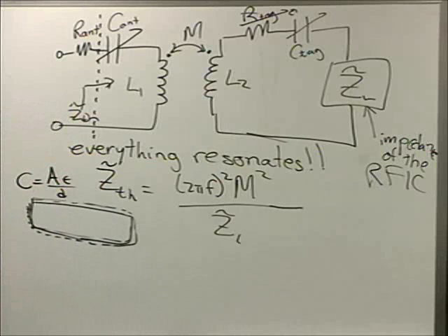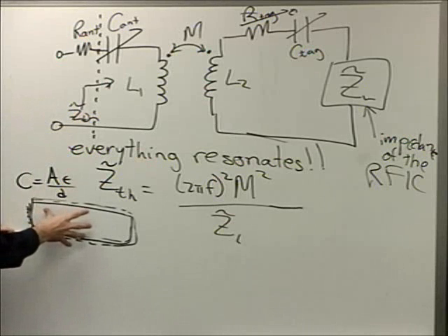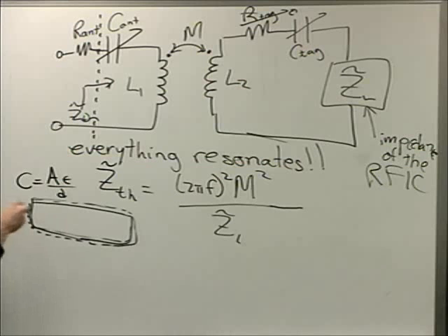So instead, you have an auto tuner that, depending on what the actual value of this over-designed capacitor is, takes a laser beam and cuts out a chunk, thereby reducing A to the value of the appropriate capacitance.